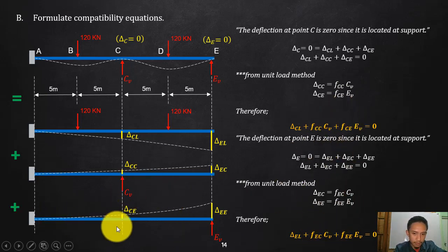So how about here on the redundant at EB? Again, we do not know that one, so assume later on a unit force, but that will eventually make this one, this beam deflected going up. So again, a positive deflection at C, a positive deflection at E. So summating all of this at C, summating all that deflection, this is negative, that will cancel out by these two positive. So that will end up with 0.